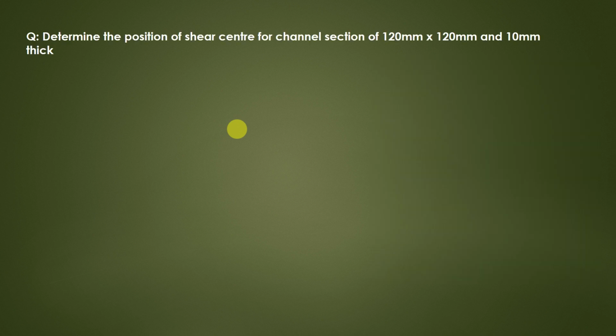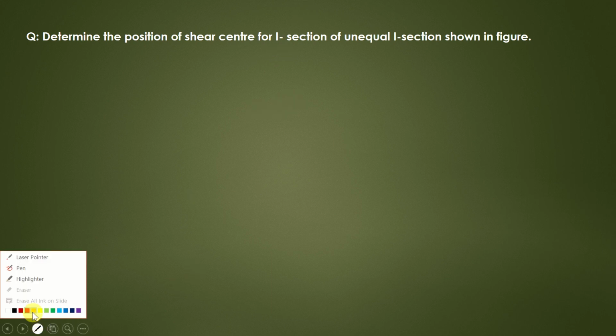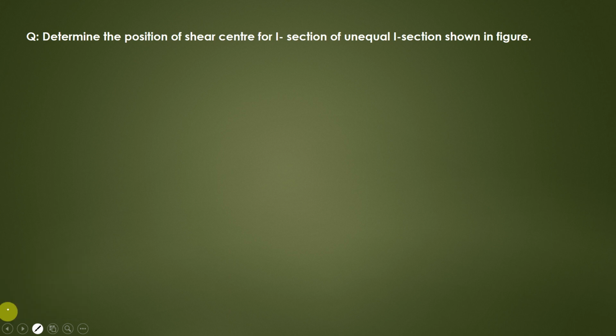Let us solve a simple question on it. Determine the position of shear center for channel section. Sorry, I forgot to remove channel section here. Determine the position of shear center for an unequal I section as shown in the figure. Let me draw the figure here that is actually given in the question. This is the unequal I section we have.